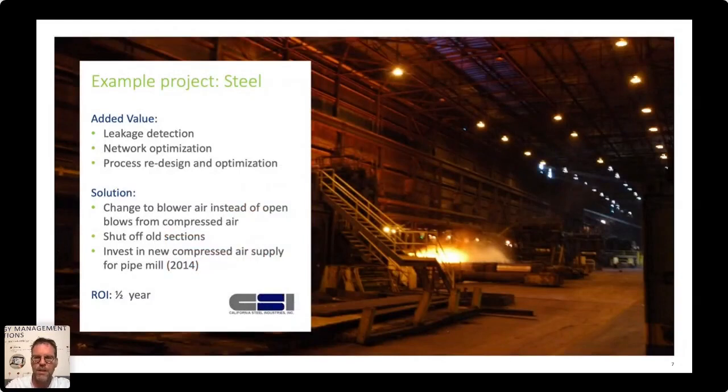This was a project we did in a steel plant where they had a big project to save energy on all kinds of utilities, one of them being compressed air. And what we found there is there were huge leakages underground in old parts of the plant, but also air was misapplied in things like cooling of material, where they could also use low pressure air generated by blowers.